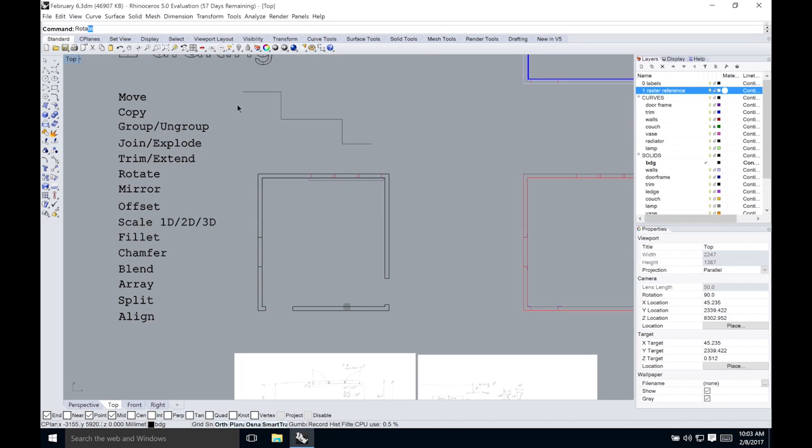So if for some reason you start using rotate 3D more than rotate, then if you don't pay attention and just start typing, which is often what I do, I just start typing the commands I know and then press enter, and don't realize that it's actually the wrong one that I'm in. So just be mindful of that. Also, the same applies to scale 1D and 2D.